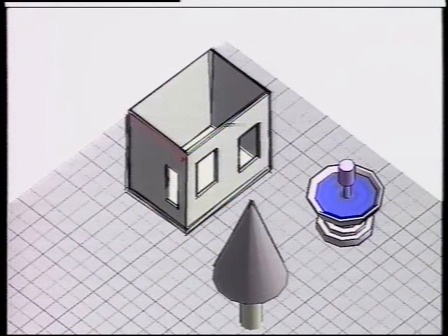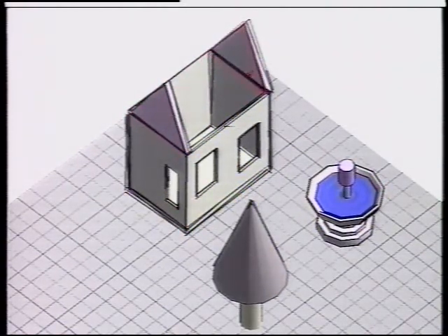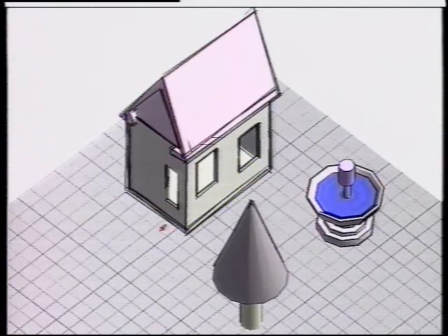Some objects, such as tubes, extrudes, and ducts, require a combination of gestures to create them. A roof for the house, for example, is created from 3 extrusions: 2 triangular walls, and the roof itself. To make these objects, we first draw a cross-section by clicking a polyline of possibly non-axis aligned segments with the mouse. The cross-section is followed by an axis of extrusion. We adjust the position of the roof slightly by sliding it with a single axis translation constraint. A walkway to the house is created by drawing another cross-section, but this time we sketch a path of extrusion.